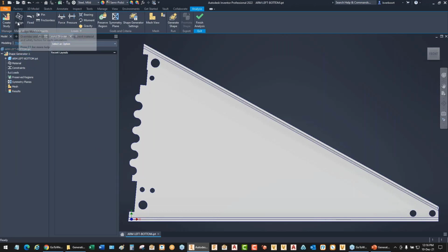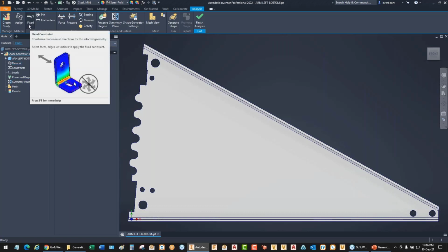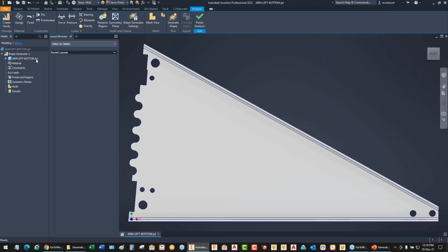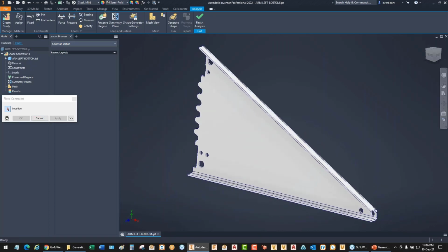So knowing the material that we have and our goal in mind is increasing sustainability by reducing material, we'll go ahead and start working through by anchoring or securing the model here that we're planning on using the generative design tool against. So as we start to apply loads, we need to constrain this model somehow in space.